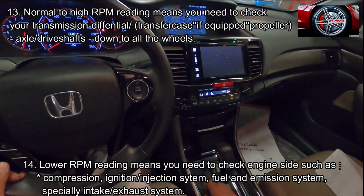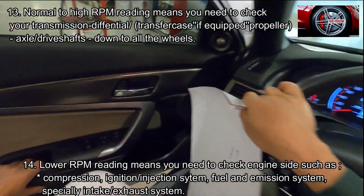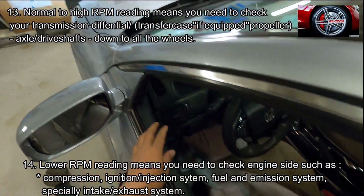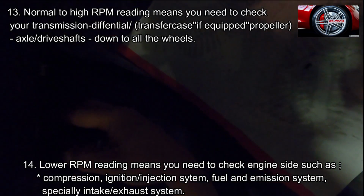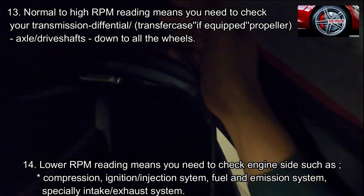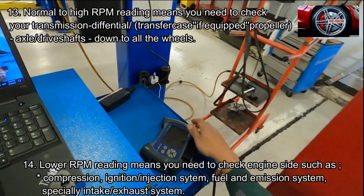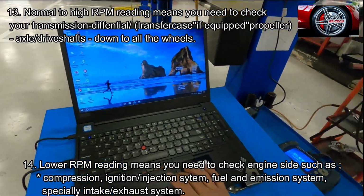Okay, wait guys, sorry, but this time I forgot to turn off the AC. It can damage the AC compressor, but luckily it never happened. So next time I have to be very careful. But you know what? With the AC on, it means there is engine load, and yet I still read 2000 rpm upon revving. So it is more likely that the engine is working very well. So again guys, don't turn on your AC while performing the stall speed test.